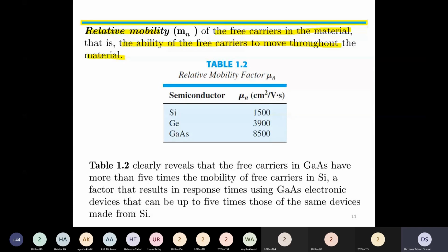We see that our electronics burn out due to this runaway effect, that as temperature increases we get more free carriers. These free carriers produce more I square R losses. If our heat sink is small, then heat cannot be extracted. This heat will be contained within the material, and hence we will get a burnt out material. Plus we need proper heat sinks.